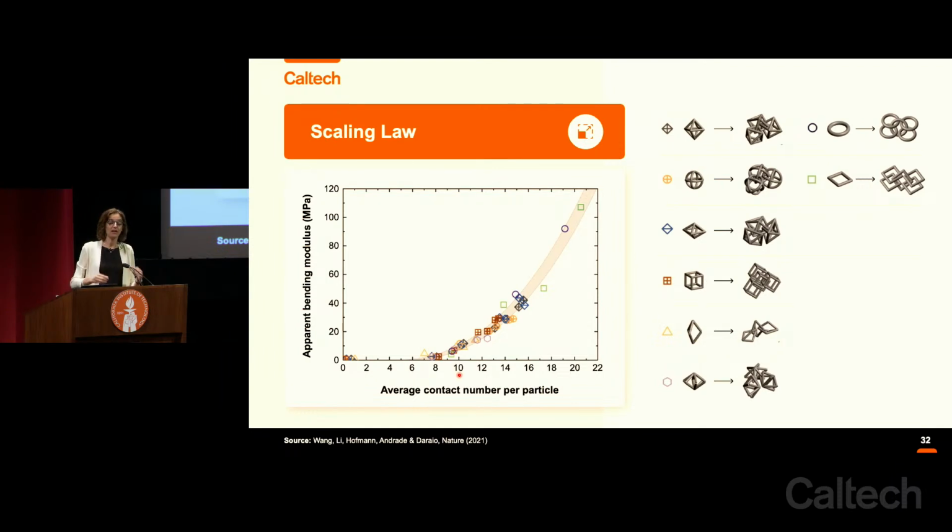And then there is a second effect, which is the material problem. Once you are jamming these particles and they are really in contact, so much so that you're squishing them like pancakes, then the material response really comes into play. So there, it really does matter, for example, if your particles are made of nylon or aluminum or steel, because that will determine at what point these rings break or deform permanently so that they become unusable in the future. So there is an effect that actually comes into play at both scales, the single particle material and the way the particles interact with each other.